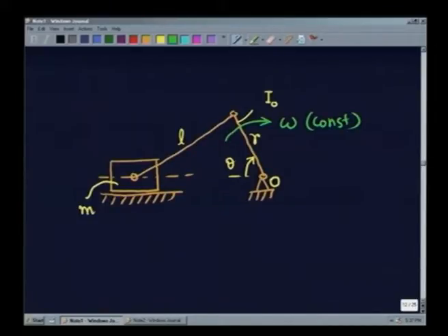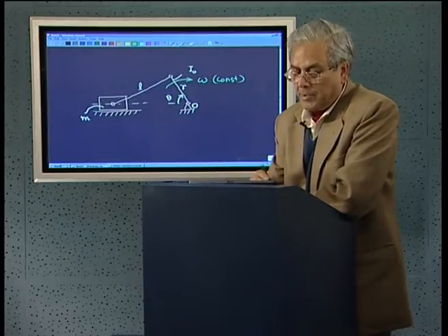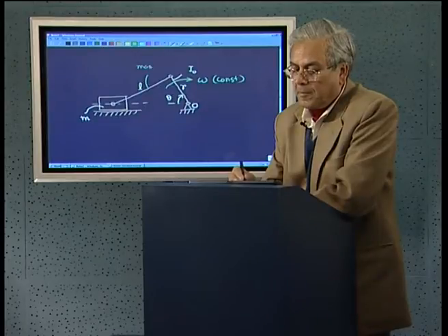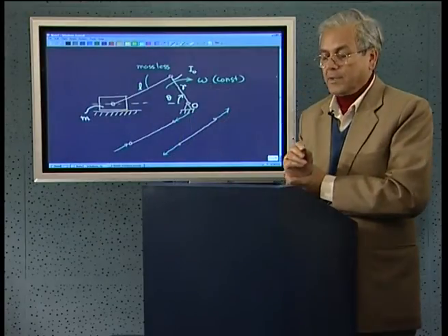Then if you have to design, say, this particular rod, how do you do it? What we will do is consider this particular rod, if it is massless for simplicity, then it will be subjected to either pure compression or pure tension, which means that the resultant force on this will be 0, because it is a massless system, it cannot sustain any resultant force or moment.